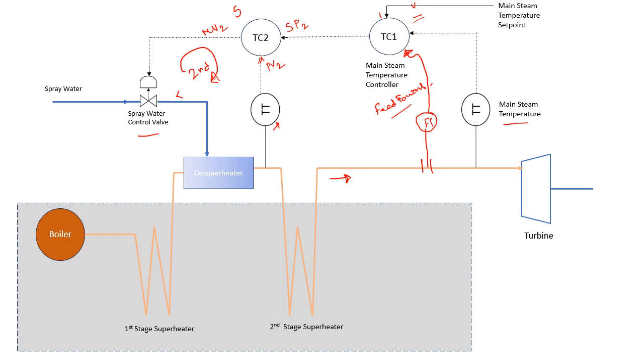So we should always use proper temperature measurement techniques, and the temperature measurement should have an overall accuracy of less than 1 degree centigrade, so that the overall loop can be maintained at least plus minus 4 degrees centigrade, because this is kind of a rule to keep this temperature within the plus minus 4 degrees centigrade, because deviation from this temperature range may impact your safety and economics of the boiler.